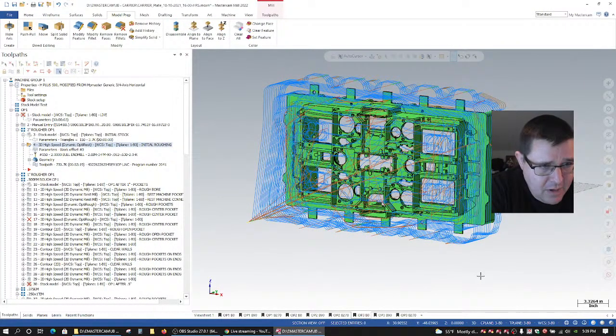Well, unless if you have to extrude something and bury a lot of features, any less overhead savings than removing the features. So the thing is, when you bury it, you have to go through a couple of stages, right? You have to do an extrude and create a body. Then you have to do the Boolean. You actually have to join them together. And then you have to run no history.